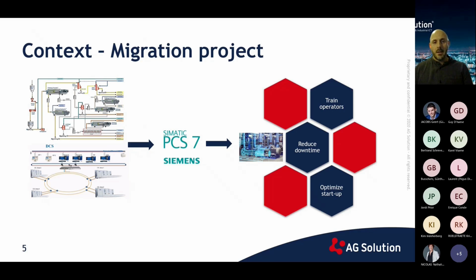Overall, the biggest impact will be the new operating system. In this story, the operator will need extensive training to get used to the new control philosophy. To make the switch to the new DCS, a limited time slot was foreseen, so it's critical to have the possibility to test the in and outputs up front, as this is typically a very time-consuming task. Another thing to keep in mind: this must be done without disturbing daily production.